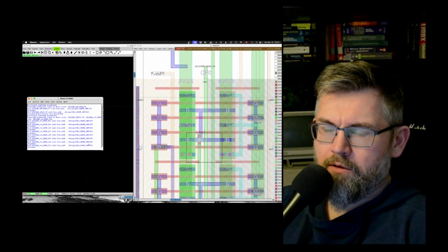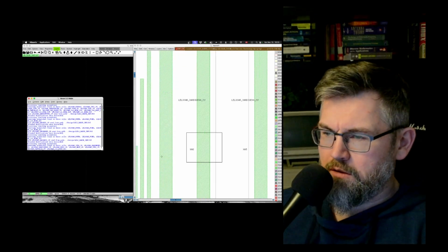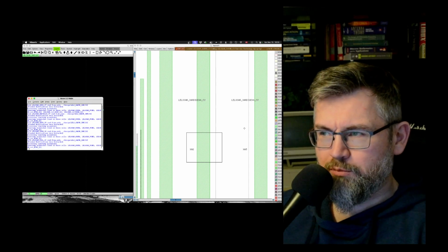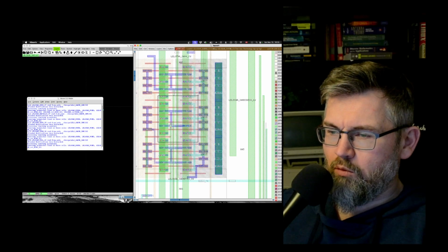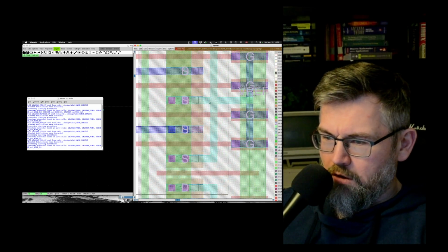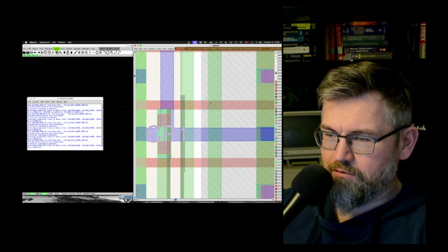So the thing about what I'm doing now is I'm really adapting the topology of the SAR layout to the specific technology. And it's really hard to predict how all of these problems are going to occur, right? Because when I made this ADC, I made it in a totally different technology with totally different metal spacing.